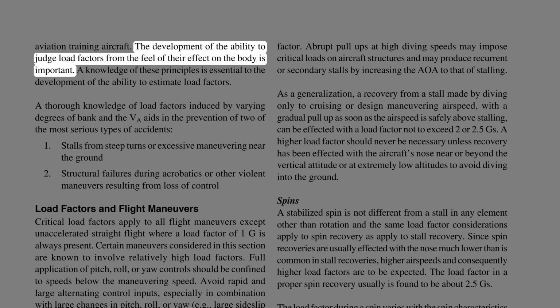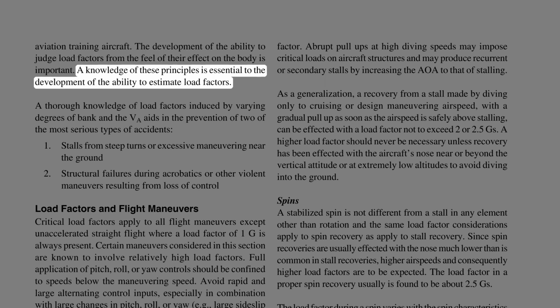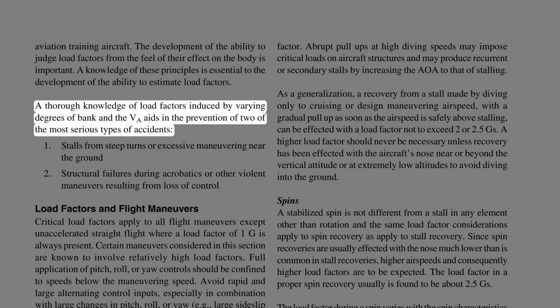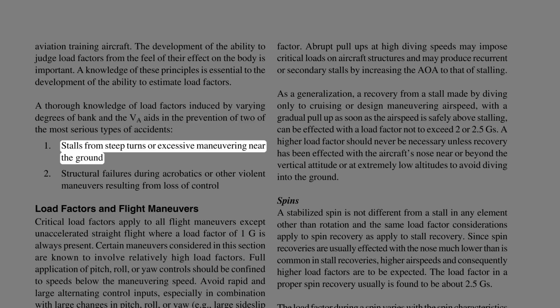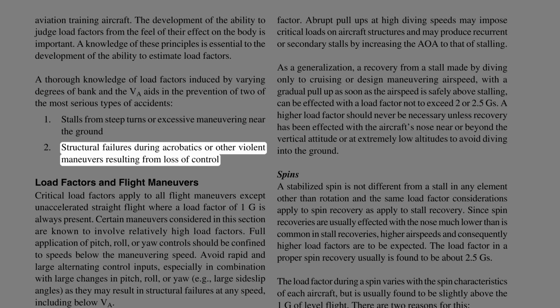The development of the ability to judge load factors from the feel of their effect on the body is important. A knowledge of these principles is essential to the development of the ability to estimate load factors. A thorough knowledge of load factors induced by varying degrees of bank, and of VA, aids in the prevention of two of the most serious types of accidents: stalls from steep turns or excessive maneuvering near the ground, and structural failures during acrobatics or other violent maneuvers resulting from loss of control.